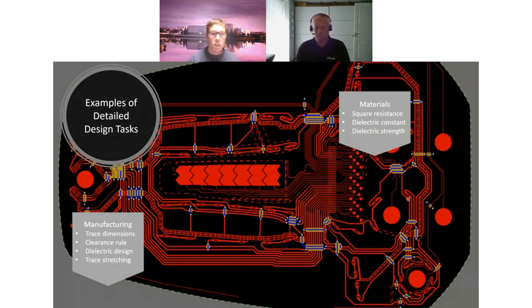When we do the 3D shape by thermoforming for the layout, at the same time we are stretching our traces, so we need to analyze what happens to the traces, and we have to design the layout based on requirements that come from thermoforming. The same is applicable for injection molding. We have to take injection molding into account, for example, by analyzing where the injection molding gate is, and design electronics around the gate properly.